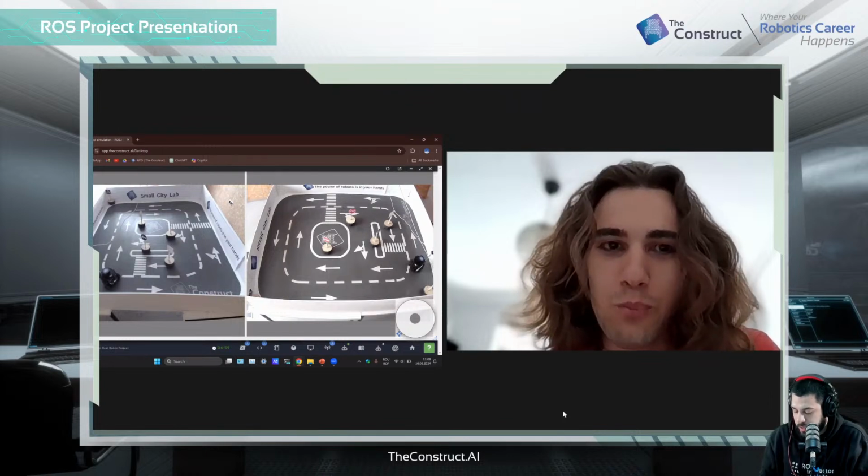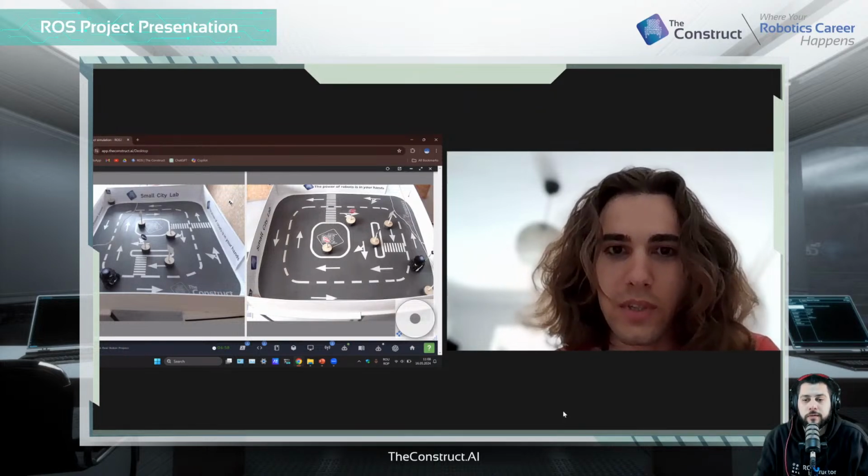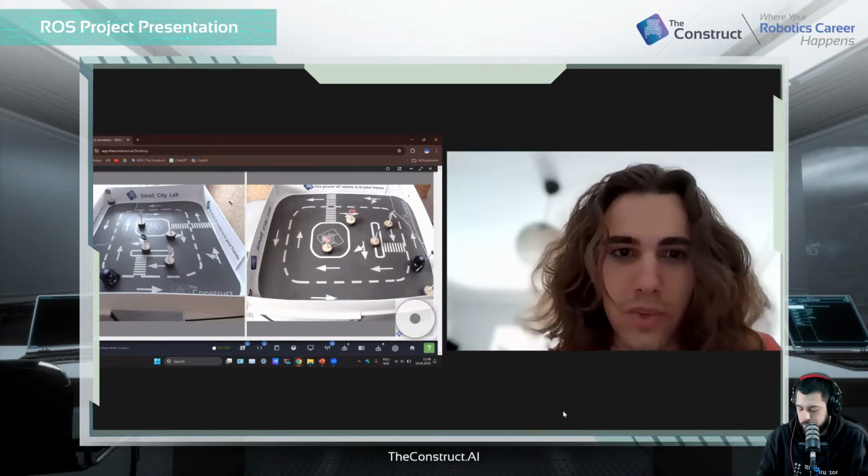And I made the PD controller because of the real robot. In the simulation everything was perfect and there was no problem, but the real robot without the PD controller was moving very wobbly from left to right, and the starting point was not really reached every time.